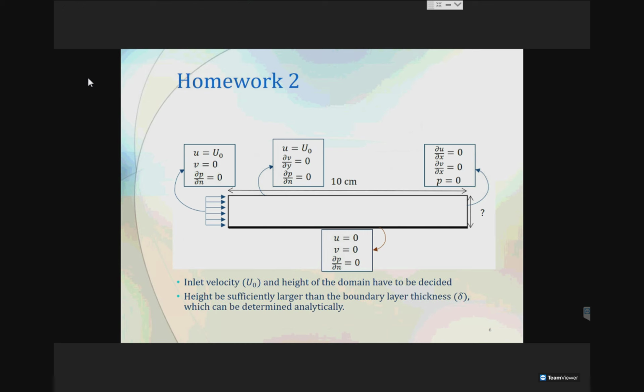So u is continuously entering our flow domain, but it cannot go forward at the same velocity because u is equal to 0 at the surface because of friction. Therefore it must go upward. It must be displaced upward. So we have to have some u and v across this as well. I have explained this point because sometimes we tend to assume that v is equal to 0 across this vertical direction. However, it is there. Nevertheless, it is very, very small.